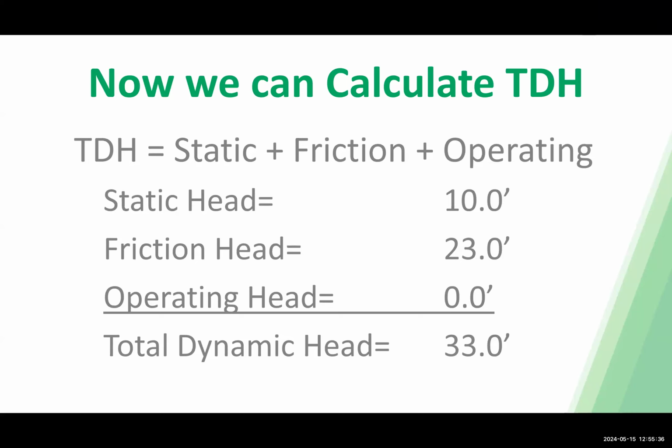Yeah, so typically for smaller motors like 1 horsepower or lower, a 1-minute runtime is usually the recommended spot. Typically those pumps aren't drawing nearly as many amps as a larger motor pump, so they're less likely to burn out. But as you get to 3 horsepower to 5 horsepower, or even 7.5 horsepower, 3 minutes runtime, and even getting up to 10 horsepower plus, a 5-minute runtime is a good target to hit.